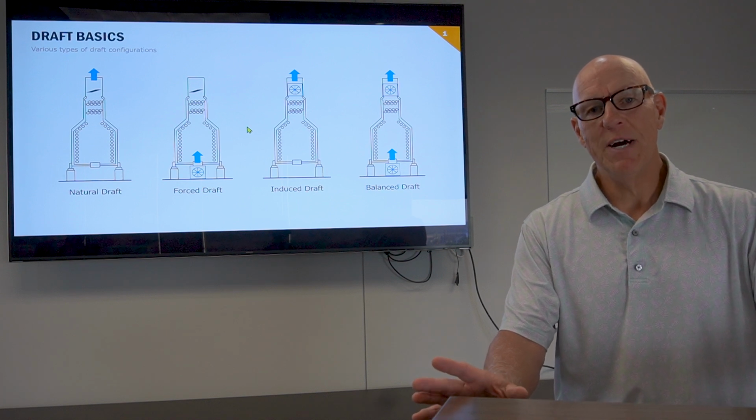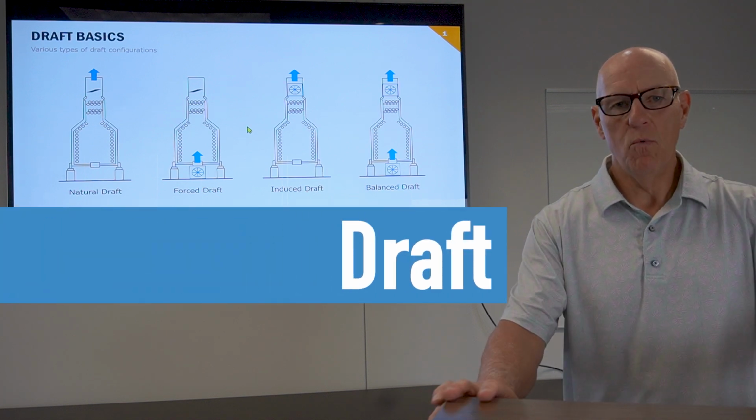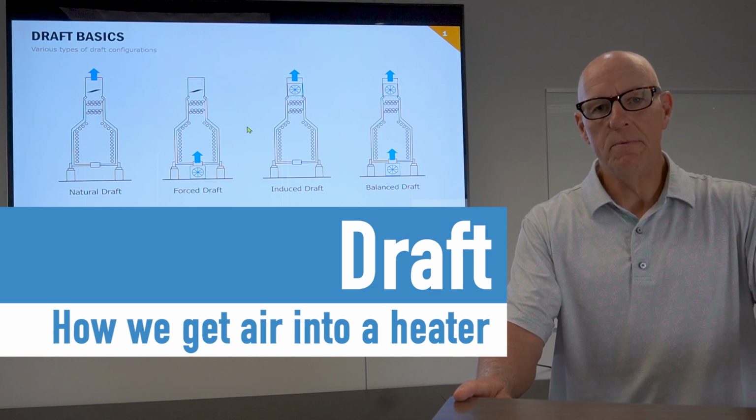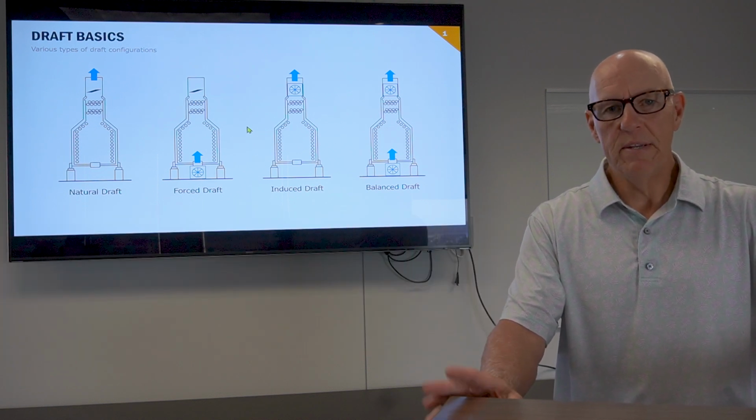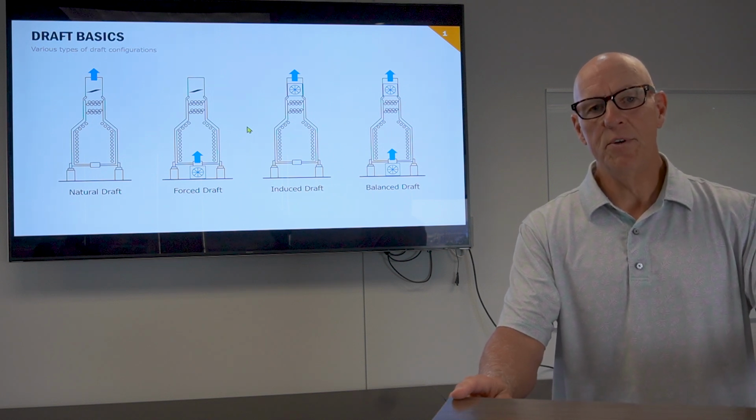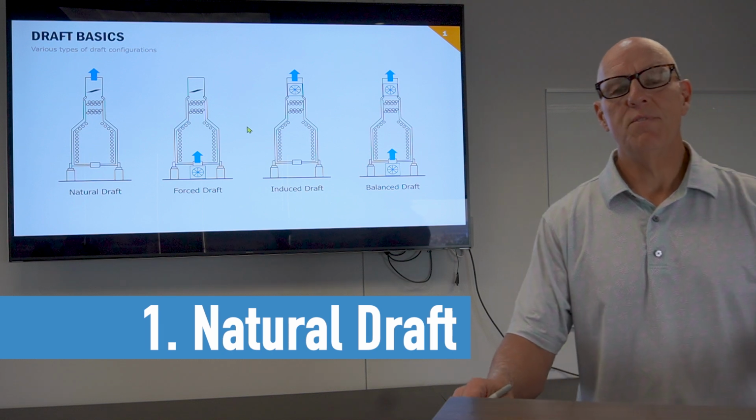Today I want to talk to you about draft, which is a word that we use to describe how we get air into a heater. There's different ways of doing it, and I want to educate you on what might be the best way for you to do that. Let's talk about natural draft to start with.